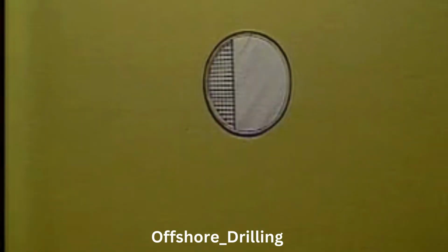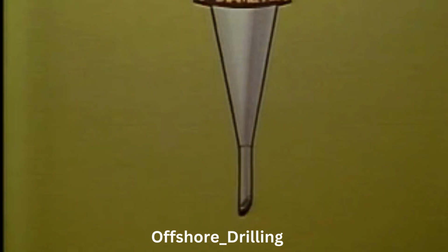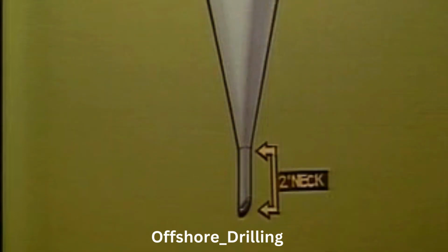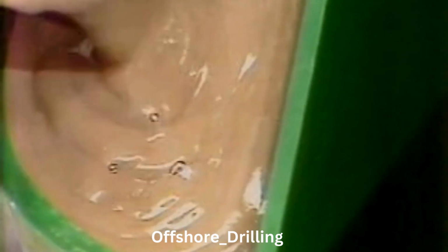Your test is made with this funny-looking funnel called a marsh funnel. It's 6 inches in diameter at the top and 12 inches long. Down here at the bottom, you have a 2-inch neck with a 3/16 of an inch hole in it. There's a wire mesh screen up here on top that's used to strain larger particles out of the mud sample so it doesn't plug up your 3/16 of an inch hole.